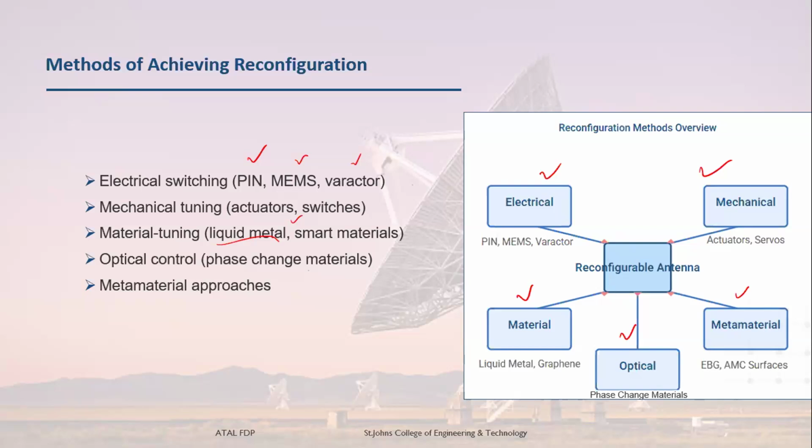When I use multiple antennas, the phase with which the signal is given to a particular antenna matters to change the pattern, shape, or direction of the radiation pattern. So that is possible. How do we change the phase? Phase change can be done through optical means also. But when I use optical, I should use materials which are sensitive to light, so when light falls on it, the phase changes. When phase is changed, the pattern direction or shape should change.